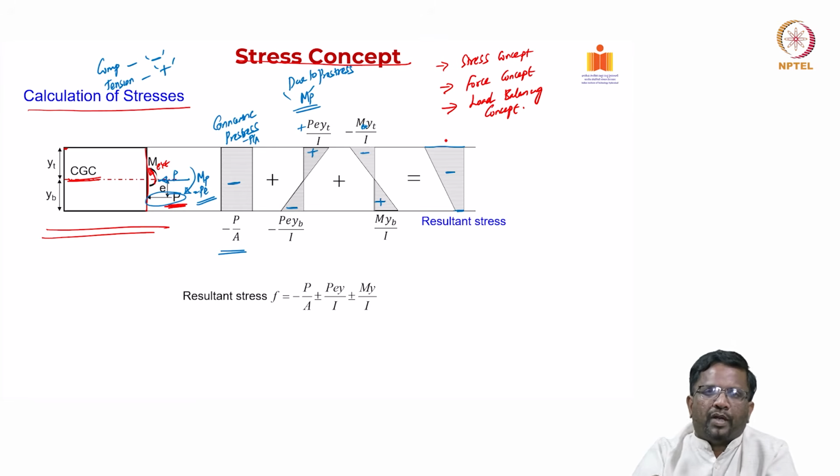If you remember, in module 1 we talked about, if you apply too much pre-stress before external loads are applied, then you will have cracking at the top for a simply supported member, right. So, we need to be careful. Too much pre-stress is also not good.